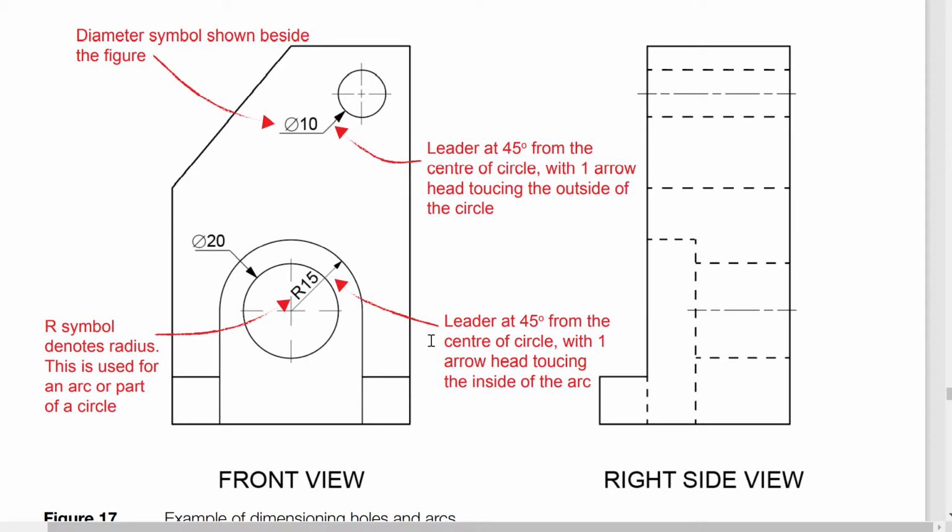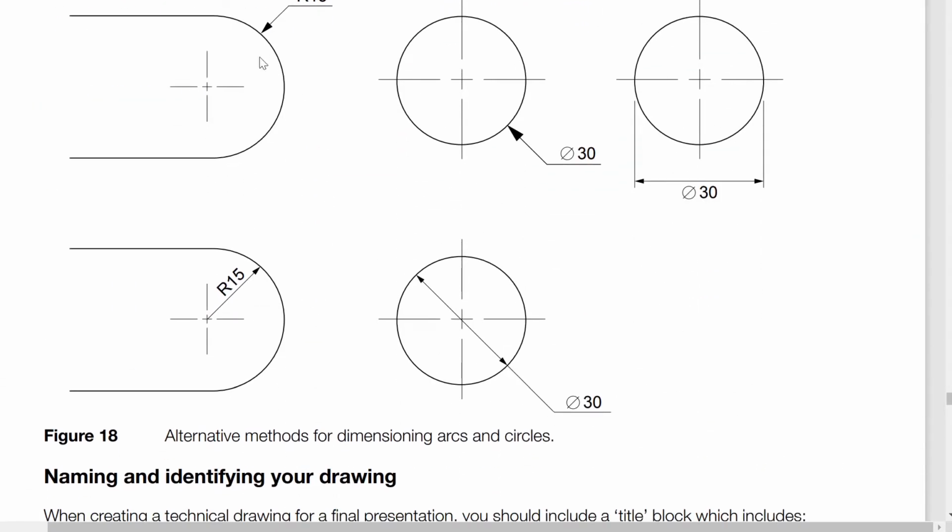We tend not to use radiuses because we never have a drill bit that's measured by radiuses. And generally, like if we have a pipe, we don't get pipes dimensioned by radiuses. Diameters are what we use. This is why whenever we talk about areas, I tell you should always use pi d squared on 4, not pi r squared. I know, because I was a student once, I know that everyone wants to use pi r squared, but let me tell you, eventually you realize that there's no radiuses in engineering, except for these radiuses, which,